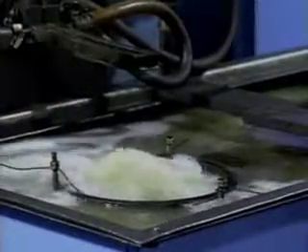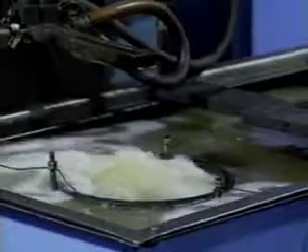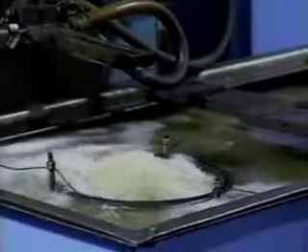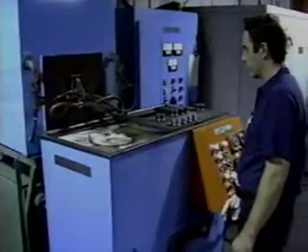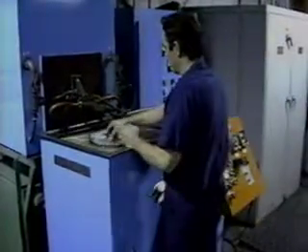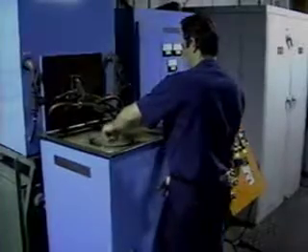Typically, it is recommended that the volume of the reservoir be 5 to 8 times the volume rate of flow. For example, if the flow rate is 10 gallons per minute, then the reservoir should be at least 50 to 80 gallons. Another problem often encountered with polymer quenchants used in induction systems is that excessive pressures are used, which effectively blow the polymer film off the part prematurely and non-uniformly, which also leads to poor distortion control.